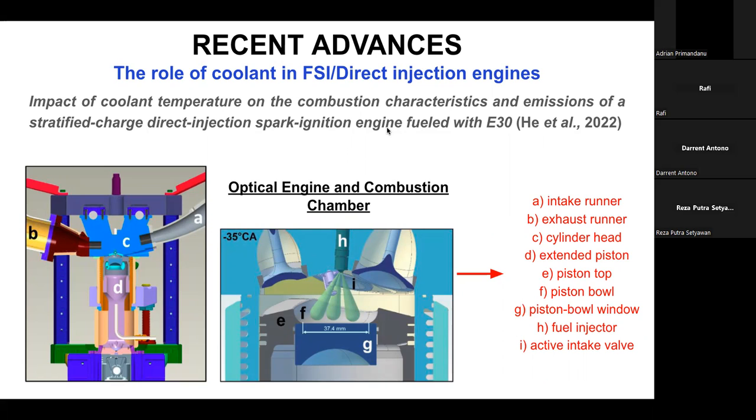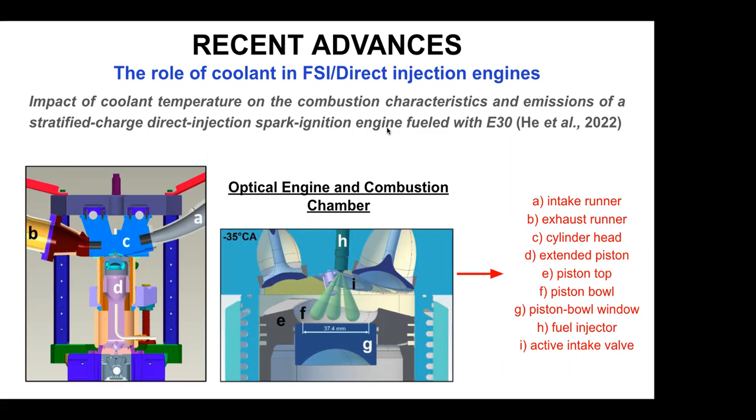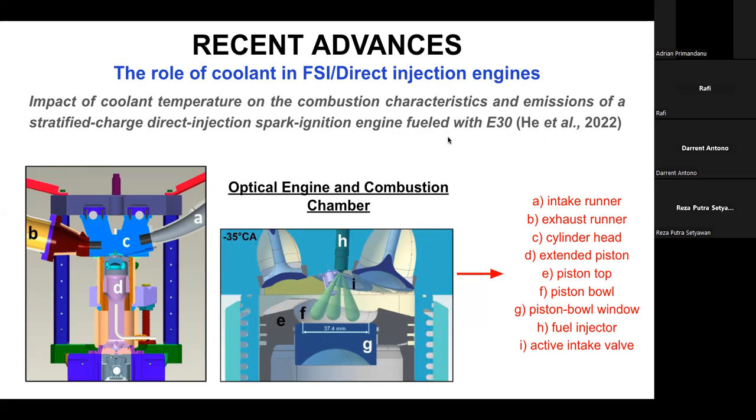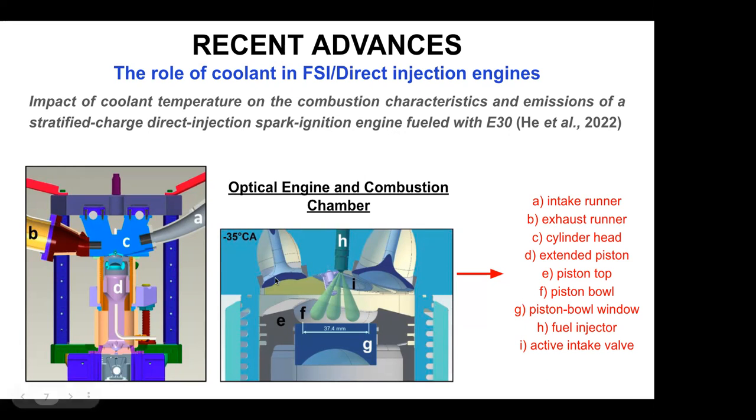Research is the role of coolant in FSI or direct injection engines. One of the studies is about the impact of coolant temperature on the combustion characteristics and emissions of a turbocharged direct injection spark ignition engine filled with E30. The experiment can operate in two modes in the study: all-metal mode for performance and emission testing, and optical mode for optical diagnostics, such as high-speed direct photography and particle image velocimetry. In this particular study, the operating parameters such as engine speed, injection, intake temperature, and pressure of the two modes were kept the same.